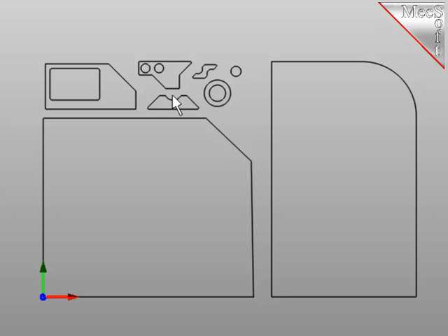I have two tips for you when you stage your parts. Number one, don't stage a part within the stock material. Keep them all outside of the material. Number two, don't stage small parts within larger parts. Keep them all separately spaced.